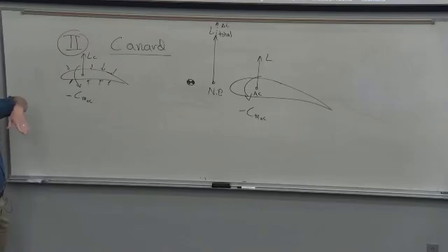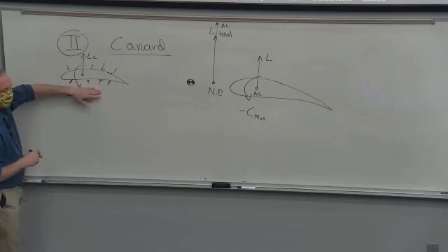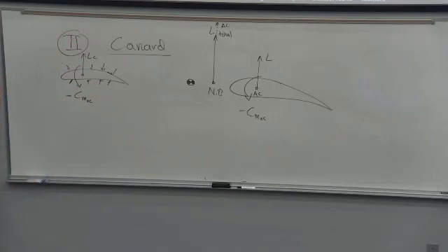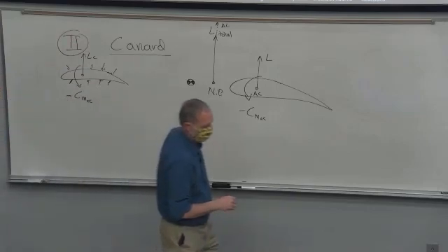Whereas with a conventional wing and a horizontal tail, if the wing stalls, you have to be careful to stall the root instead of the tips, and there's some other characteristics of that. But this does help out with stall because this will stall and then it'll drop you back out of stall pretty quick. Yeah, what was the question?